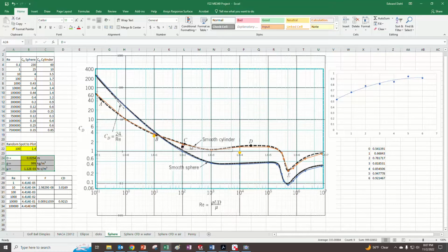to try to do. Because I had problems over here at 10,000, I'm going to go for 1,000. So I'm going to go with a Reynolds number of 10 to the third, and for a smooth cylinder, we're going to expect a drag coefficient of about 1.